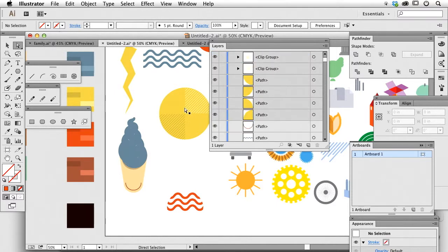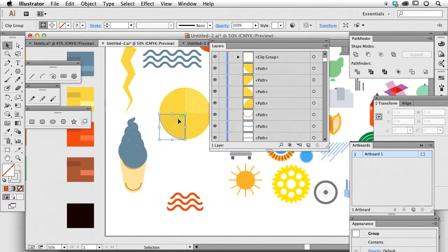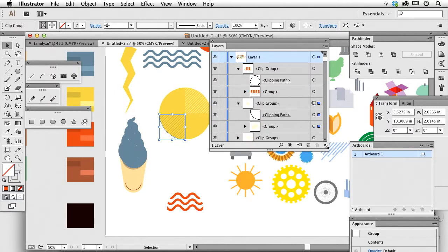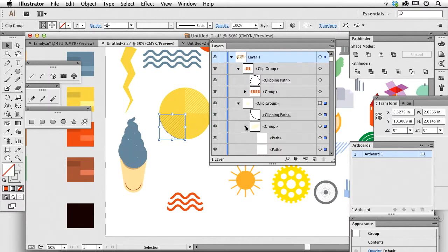So this little group that we did right here, and here's one of the reasons why I group things together. With all these lines in here, before I did my clipping mask, I just grouped them out of habit, and that habit is this. When I select something here and I go into my layers panel to see where things are, and I know where they are in the group here, and I open it up, do you notice how all those lines are in a group? If I hadn't grouped them all together, I would have 30 layers of line, line, line, line, which makes it really difficult to navigate through the whole thing. But because it's in the group, I can specifically select that group.